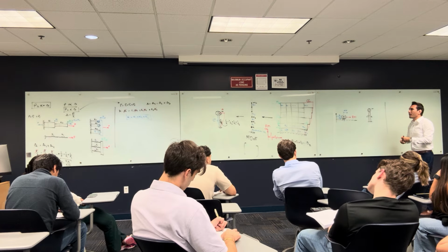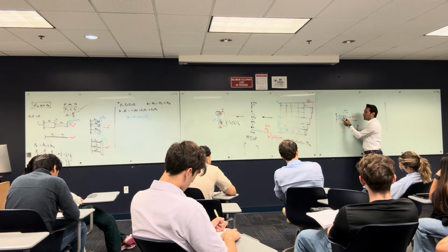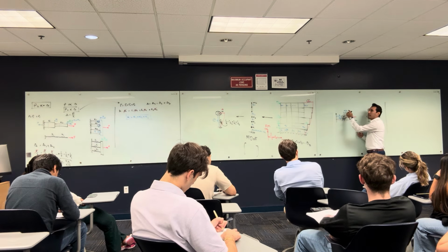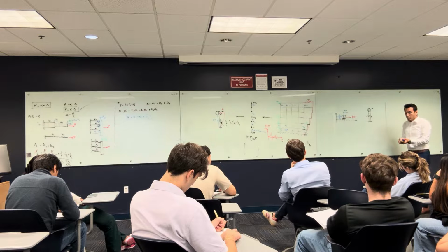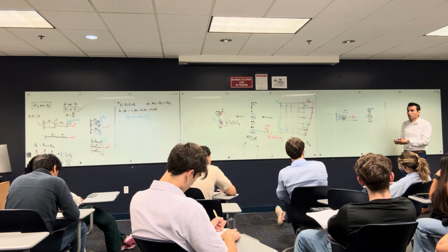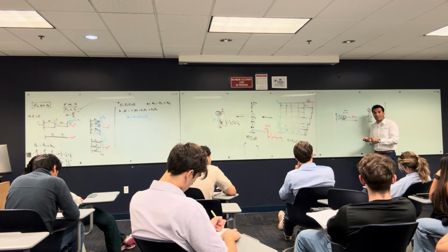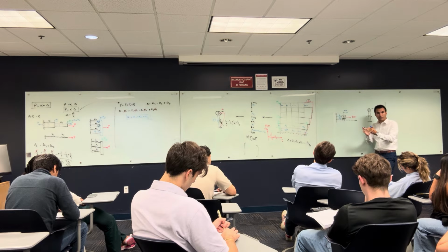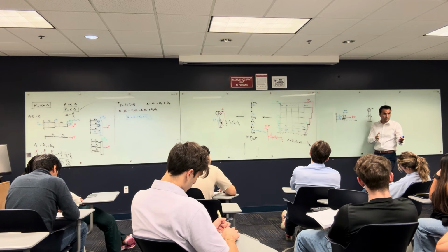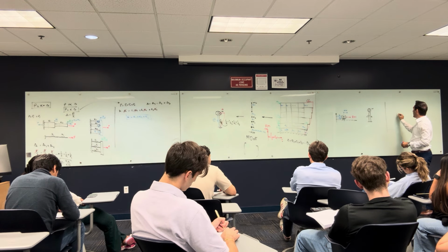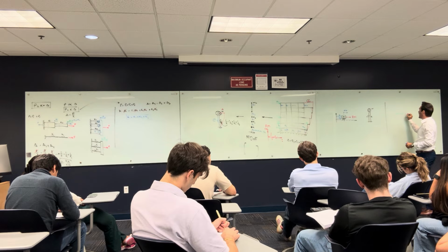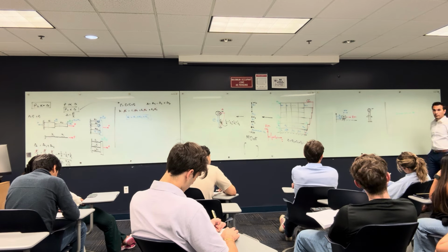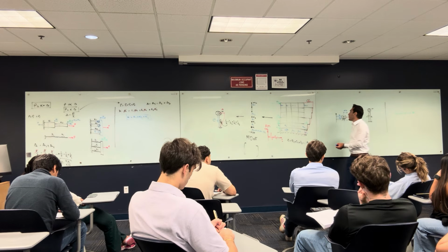Alright, so my mission right now is to solve this structure with this mass and this stiffness and this damping coefficient to find the acceleration of the structure. Because if you found the acceleration of the structure, you can find the velocity and you can find deformation. Because there's a relationship between A and V and displacement, right? If you found the acceleration, you can integrate the acceleration and get velocity. You can integrate the velocity and get deformation. Alright? Okay, so how can we solve this?